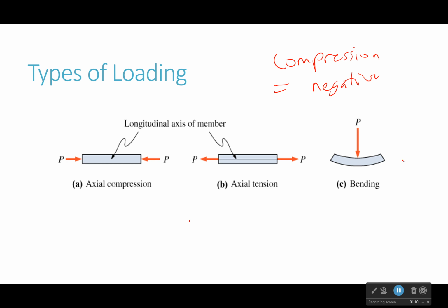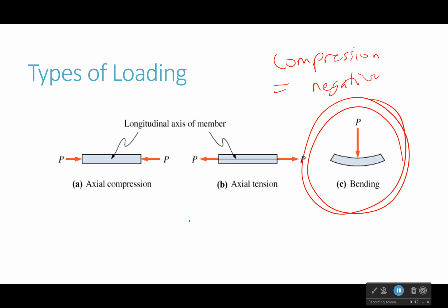The last thing, which we're not going to see, at least not right now, is where there's a force that's applied crossways on a beam. These members that we're looking at are two-force members, which means there's only a force along the line of that member. This bending throws that off. So that would be what's called a three-force member, or multi-force member. We'll learn about that later, but not today. So we're not going to see that for what we're learning about today.